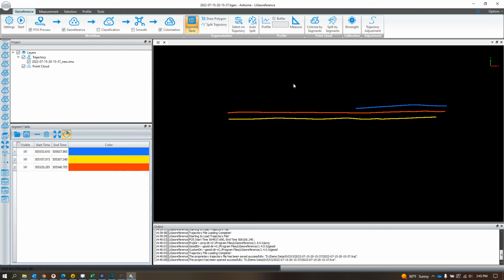There are a couple of different ways you can do it, and it really depends on your software and how your workflow is. But in general, I just want the georeferenced colorized point cloud, and then I will remove noise or outliers and things like that in a third-party program where I'm going to do my extraction too. There are a lot of ways to do it, but again, it's a whole other video.